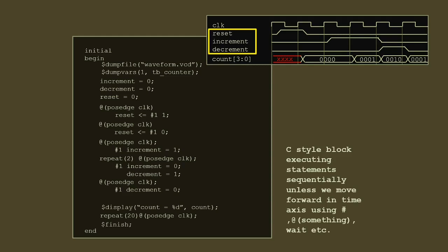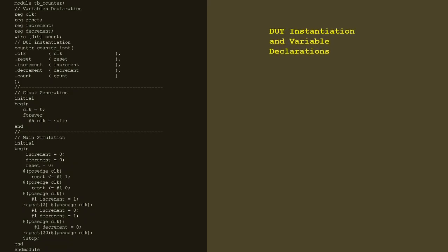The purpose of this test bench is to find bugs by using these simulations before we go to the synthesis step. When we synthesize the design and put it on an FPGA, we can't see things that easily. So that's why we have these test benches. So in a nutshell, we did 3 steps. We instantiated our device under test, that in this case was a counter.